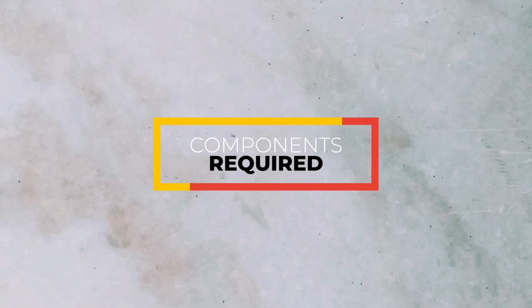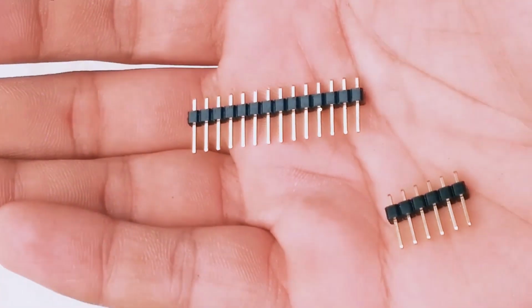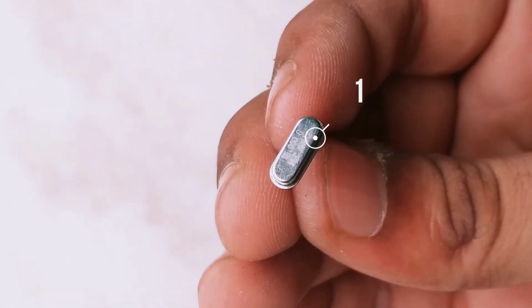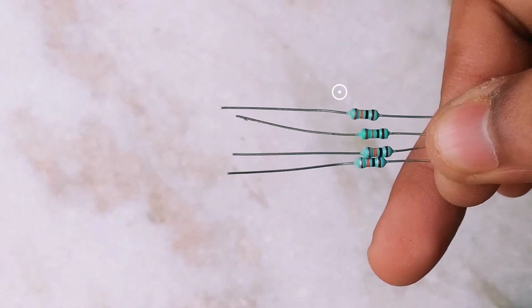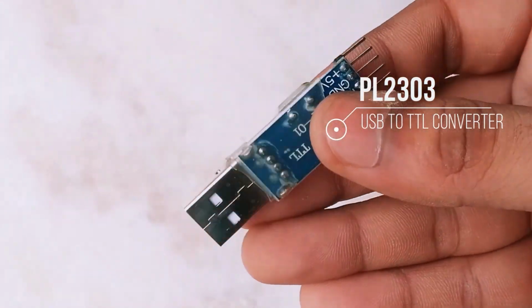For this, we will need the following things: Atmel 328P with a burnt bootloader, a 28-pin IC base for the Atmega chip, a 6x1 and a 14x1 male header, a 5x1 female header, two 22 picofarad disc capacitors, a 16 MHz crystal oscillator, 3 LEDs, 3 10 kilo ohm resistors, a 6x9 perf board, and a USB to TTL converter PL2303.